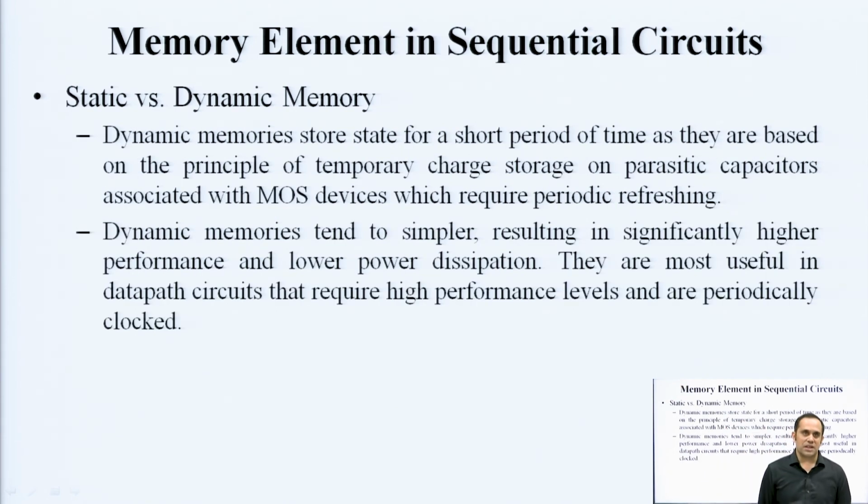Dynamic memory, on the other hand, uses a capacitive mechanism. Data is stored as charge on a capacitive circuit, which is continuously refreshed to avoid discharging. Any sequential circuit which uses dynamic memory is a dynamic sequential circuit. They are quite useful, more often used than static memories.